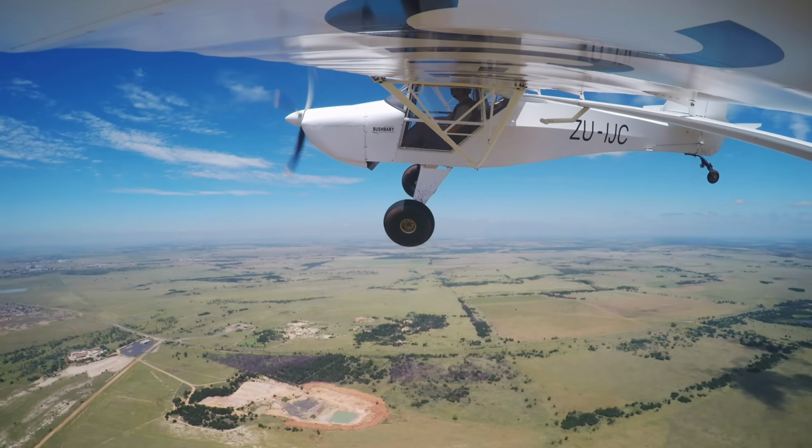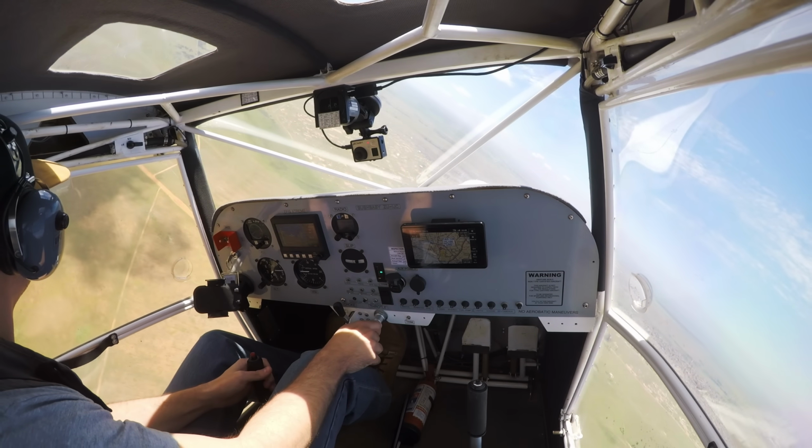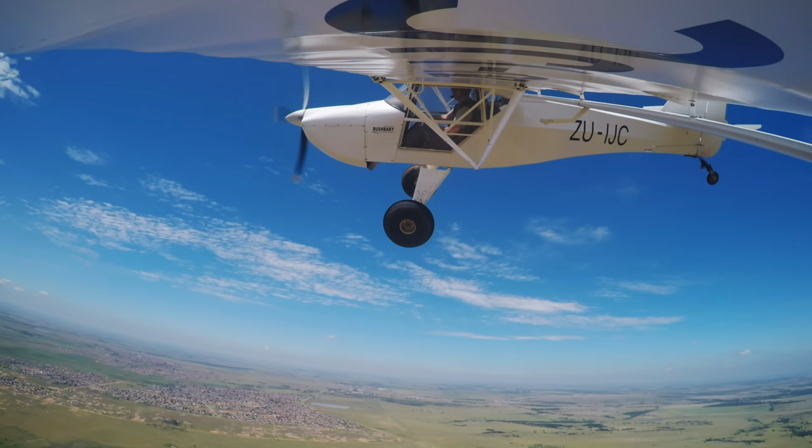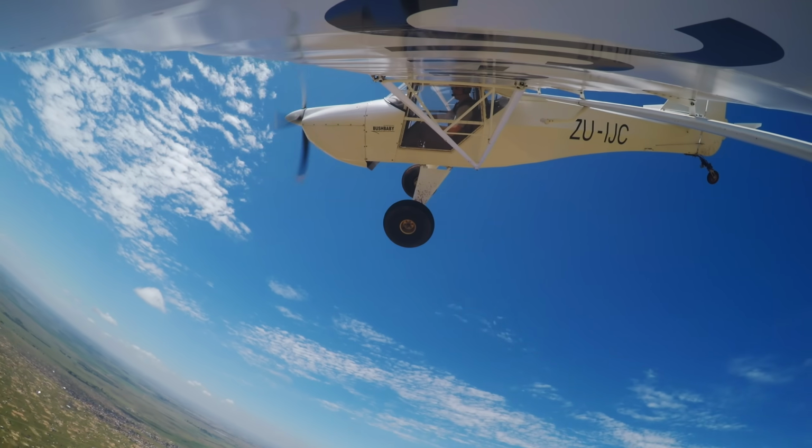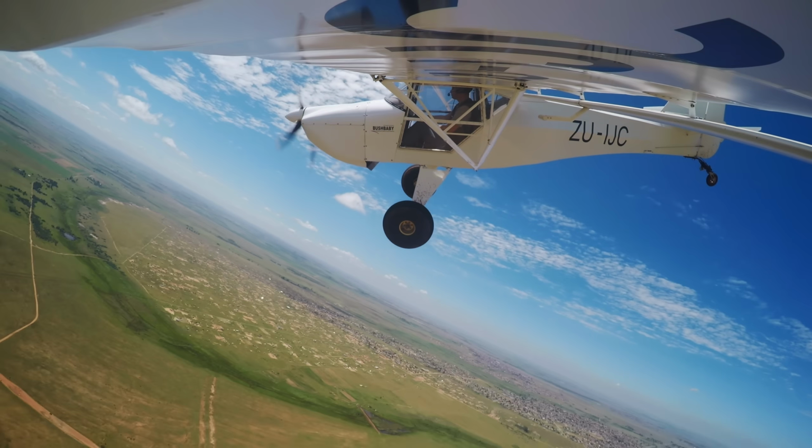Without that context, they are misleading and promote fear of banking an aircraft without offering any explanation as to why we should be careful with high angles of bank. The truth is, an airplane can be in a 60-degree bank and still fly safely below this published stall speed for that bank angle. It's not the bank angle that stalls the wing, it's the elevator input. If maintaining altitude is not a requirement and you keep the stick neutral, it can't stall.